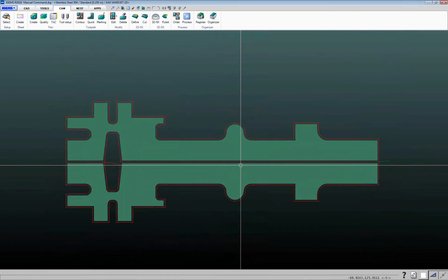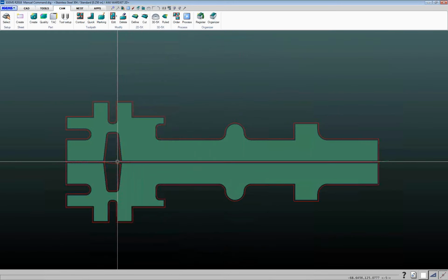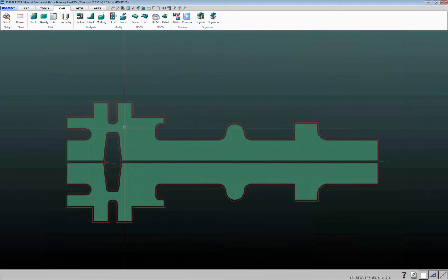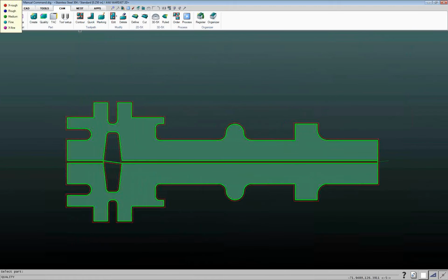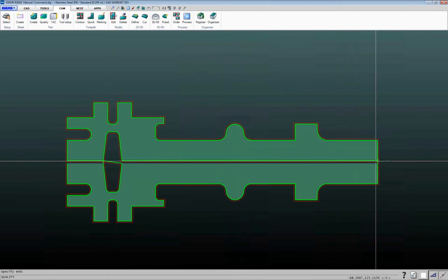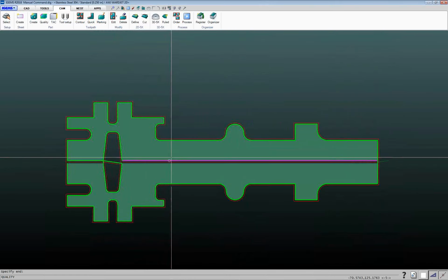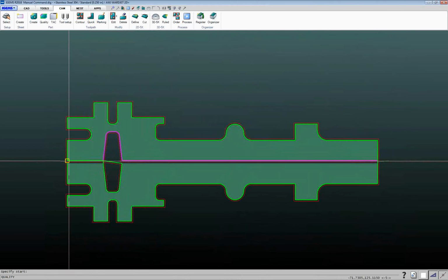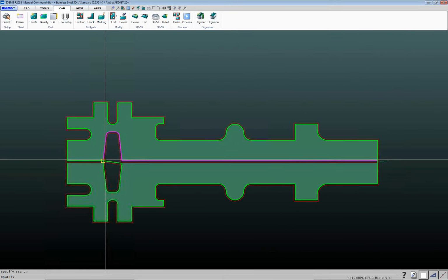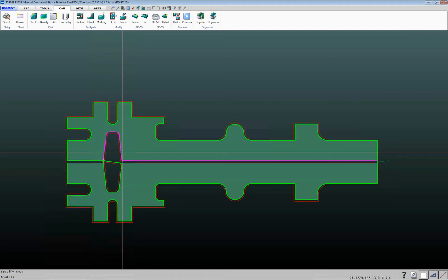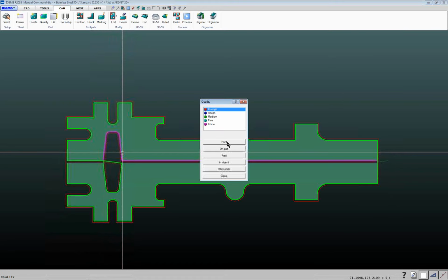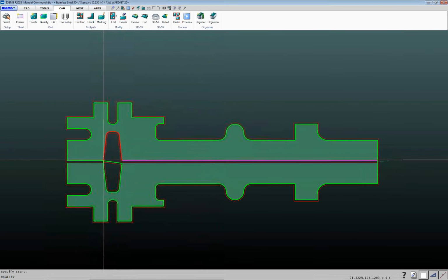So in that way, we're able to do this as a common cut, one pierce, cut the two parts, and then what I would do is I can use my quality command, and then I can adjust my quality based on what I want on my different edges here. So if I do my extra fine from somewhere over to here to somewhere over to here, I can go through and define all that, and then areas where it's not so important, then I can change to different quality here. So we'll do extra rough from here over to here, and things like that.